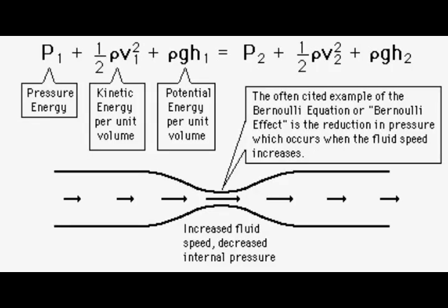Next, this pipe flow simulation is related to the Bernoulli equation, where we want to measure the pressure and magnitude velocity. According to the Bernoulli equation, the fluid velocity changes when an incompressible fluid passes through pipes of various sizes. The system accelerates as a result of this change, which changes the stress and pressure acting on the pipe's cross-sectional area. We can calculate flow rate using the Bernoulli equation, where the pressure, kinetic energy, and potential energy of the first pipe are equal to the pressure, kinetic energy, and potential energy of the second pipe.